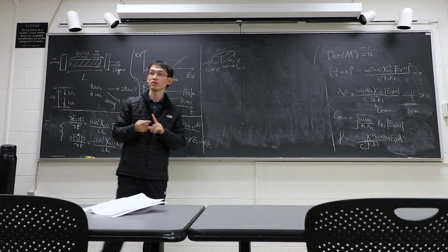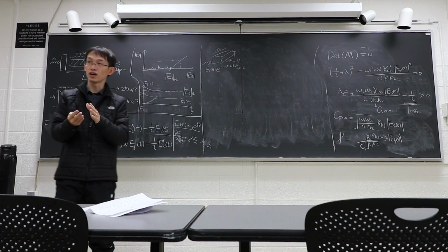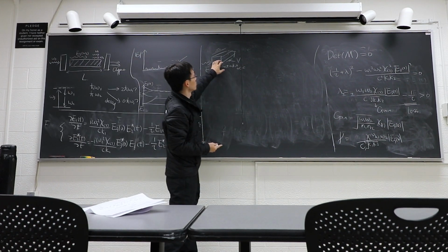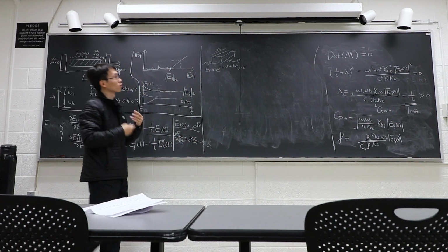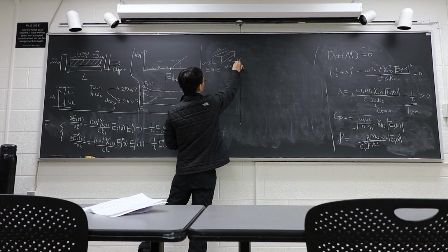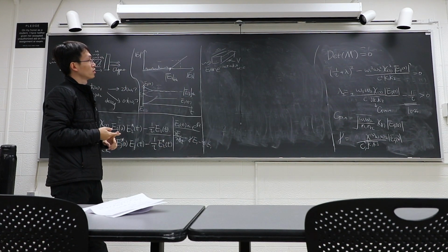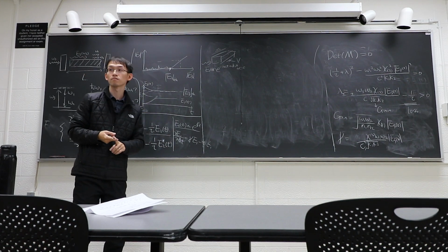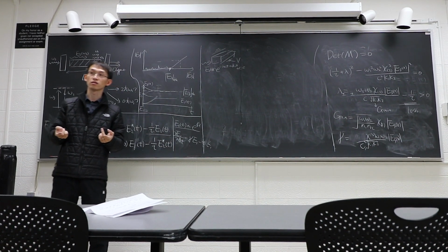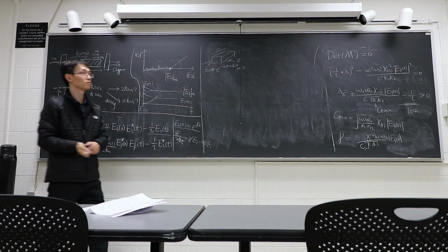And the critical difference between the thermal effect and this effect is that the thermal effect is very slow, because it takes time to heat up something. This one usually works at least to like 100 gigahertz, so you can apply a very rapid change. Let's say within 1 nanosecond, you flip the voltage, and then the refractive index will flip.